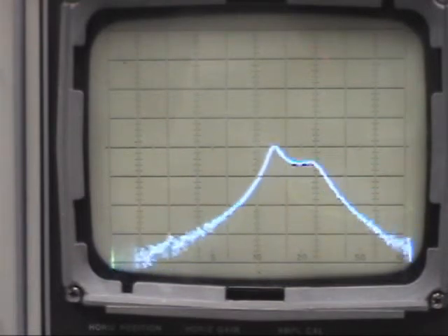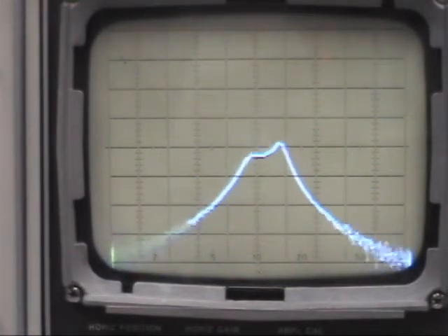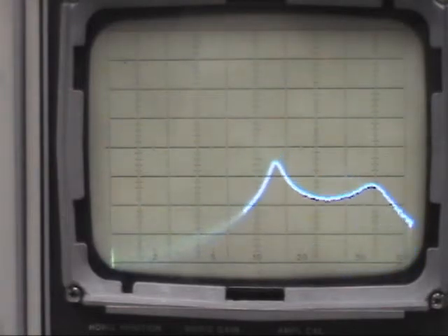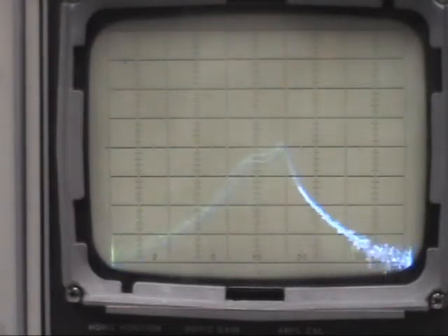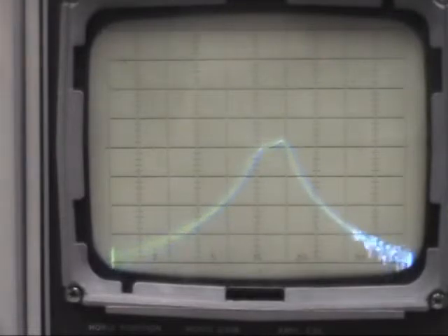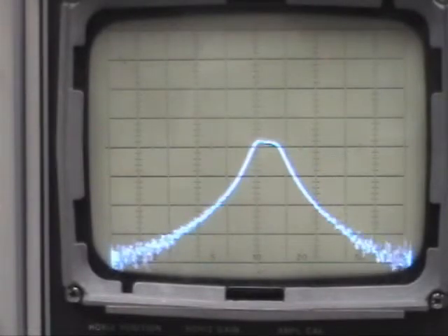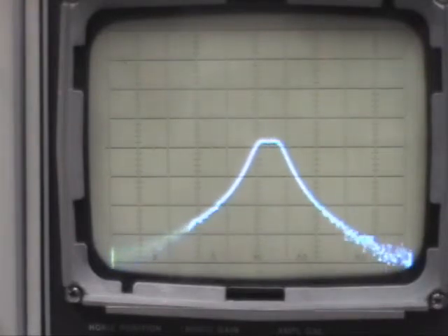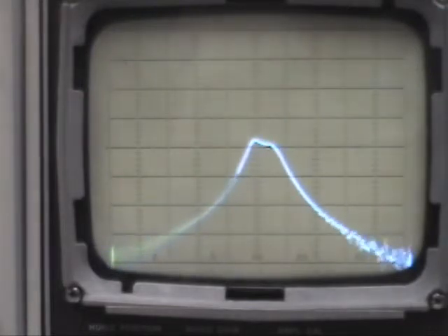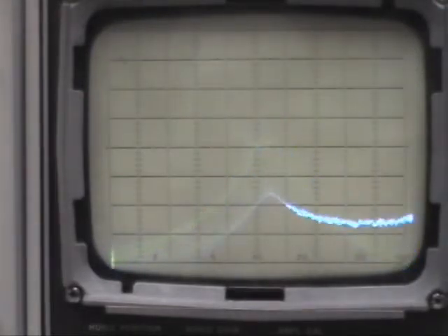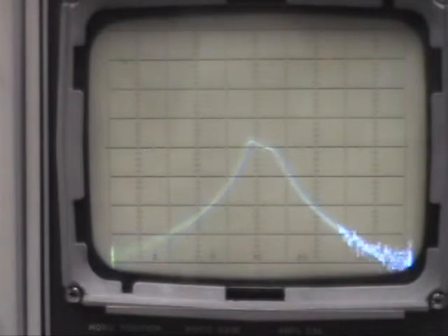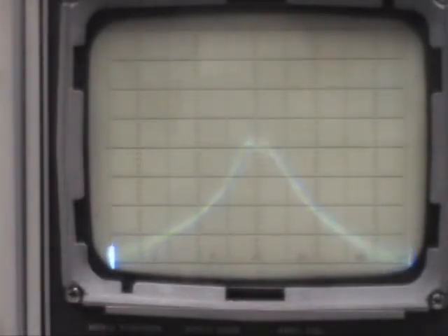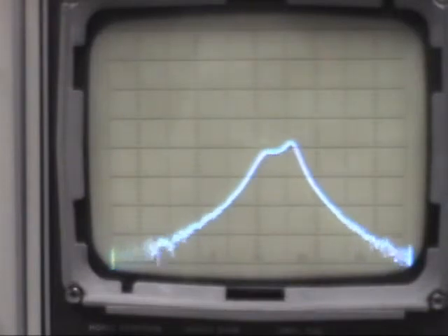But as you can see, that section's probably okay because I can tune all the way through both sides. This section, I hit the end of the capacitor, so I may have a problem in this section. That way I can tune it out. This one I'm right in at the limits too. So I'll make it flat.